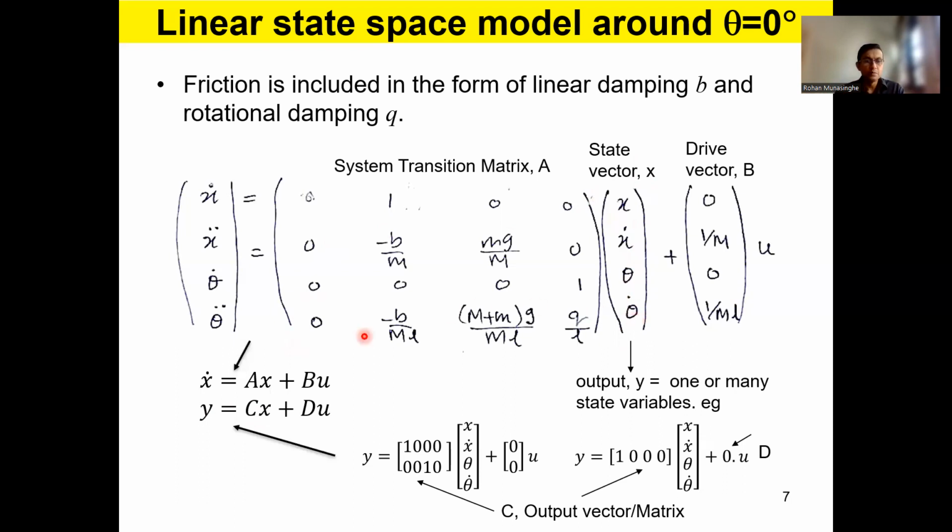That is why you can judge what you want to measure. For example, if you set your measurement matrix, in this particular case a matrix C, like this, with 1, 0, 0, 0 in the first row, and 0, 0, 1, 0 in the second row, what you are saying is that you are picking the first state variable and the third state variable to measure.